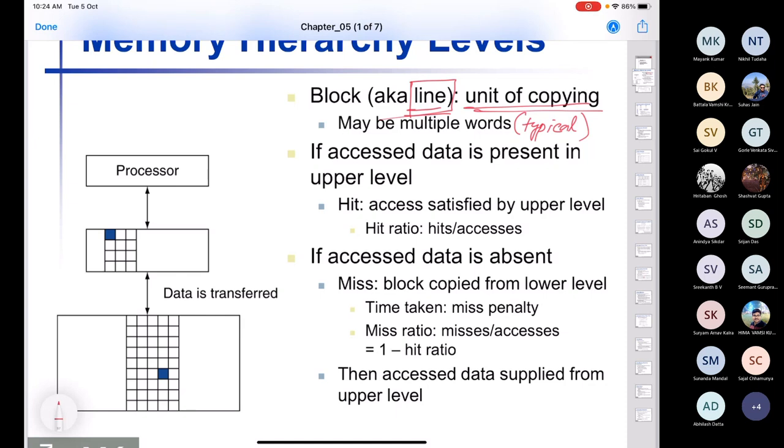Now, because the cache is inside the chip, ideally I would have liked everything to be inside the cache memory. The cache memory is a small SRAM-built memory. SRAM is a very fast technology. Every SRAM bit can be implemented with about 6 transistors. Every DRAM bit can be implemented using one transistor.